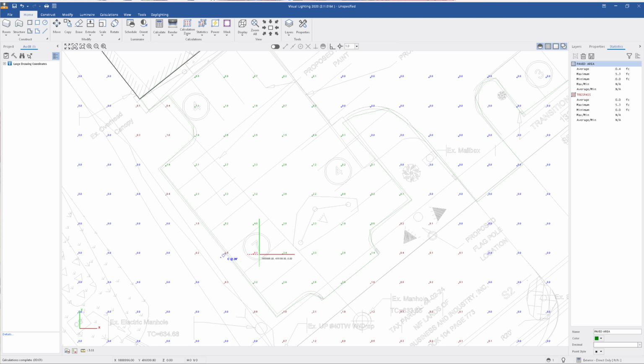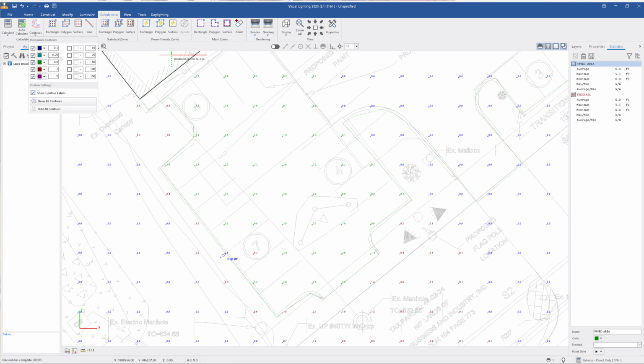But I don't see the contours. So let's see. We go to luminary, nope, calculations, then contours. And you can actually customize what numbers you want to see. I typically leave them alone. Sometimes I move the 0.25 to 0.2 because that is what a lot of times is allowed at trespass zones. So I can see exactly what's going on. But 0.25 helps also because you can kind of push it a little bit closer. And then you hit the show contours button.